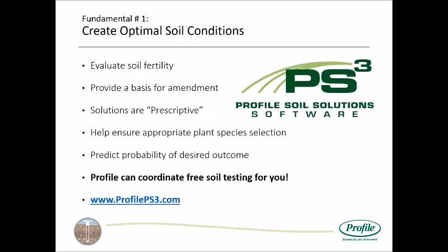So, creating optimal soil conditions. One of the favorite quotes I've ever heard regarding soil and its agronomic potential is: if you're a doctor and you create a bunch of prescriptions and you really haven't diagnosed any issues, that's called malpractice. A prescription without diagnosis is malpractice. So many specifications I see are just based on what we've done in the past. We put out 2 tons of agricultural limestone for no real reason. We think it might be acidic, but without that soil test confirming what you think, you may be doing more harm than good on your site.